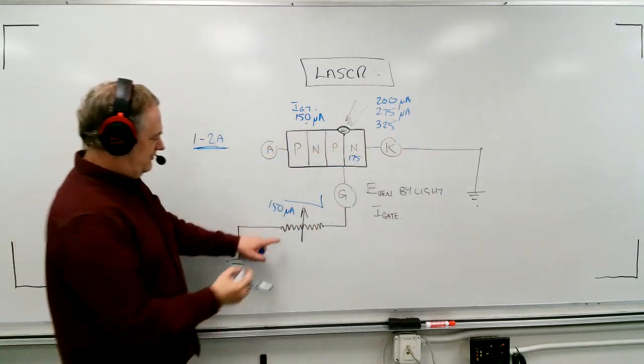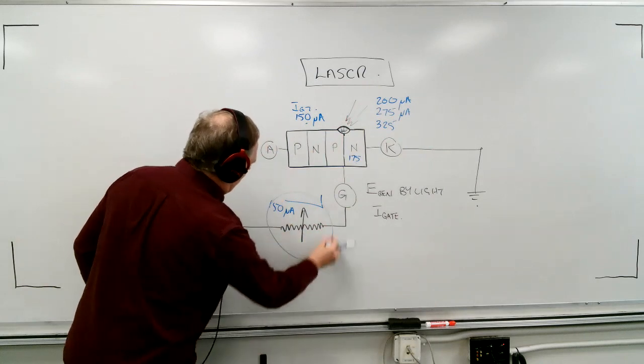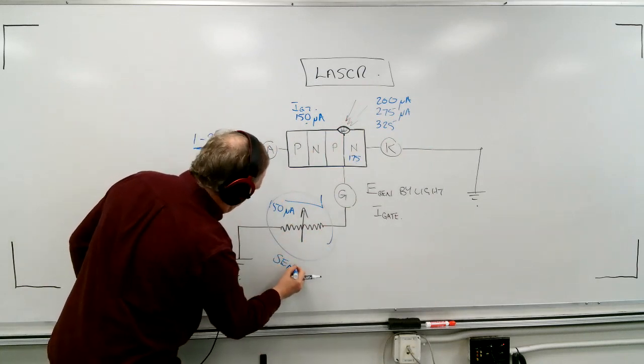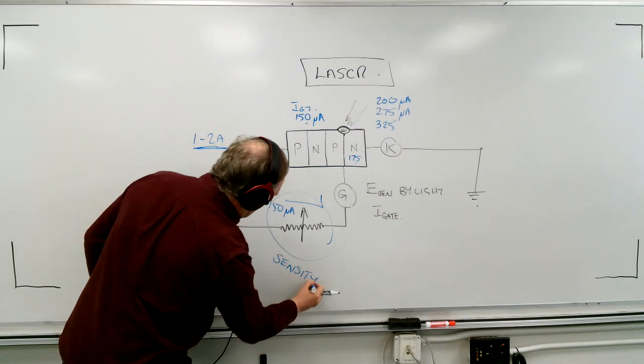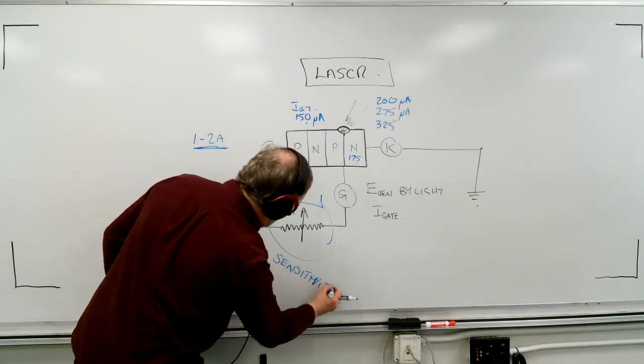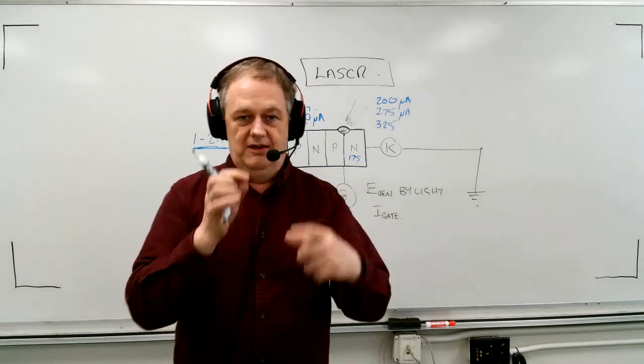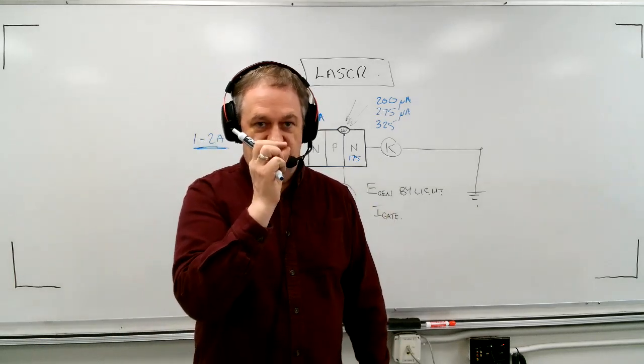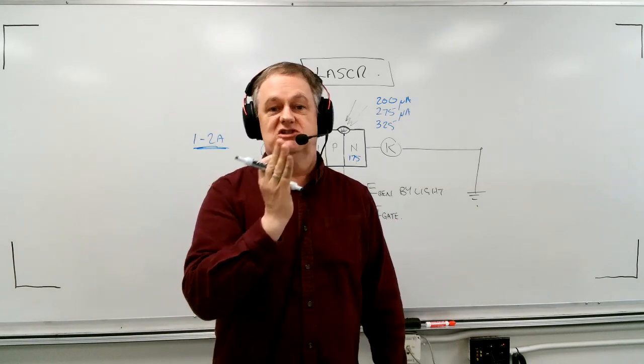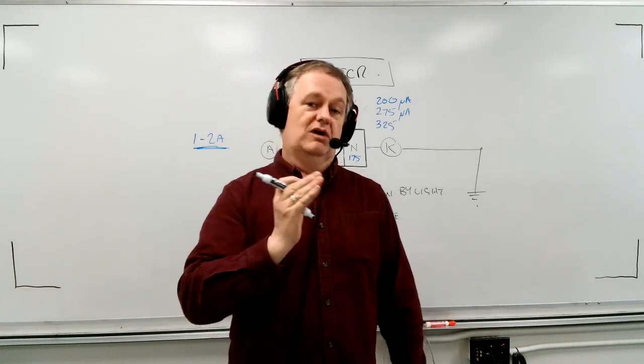So what did we do with this dial? Well, this is just a sensitivity dial, and you'll see this normally on a photo eye. Normally, when you take a photo cell, there'll be a little dial somewhere. You've got to dial that thing, and that will adjust your sensitivity to be more sensitive or less sensitive.